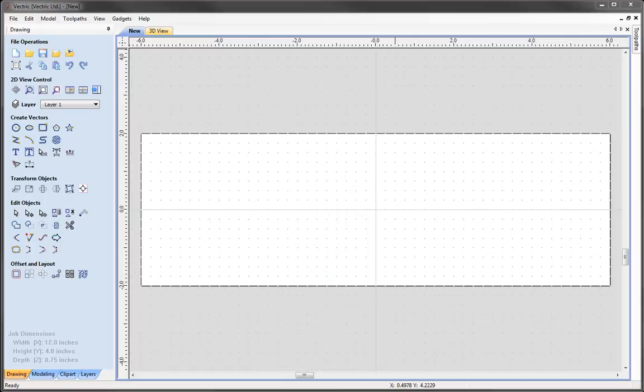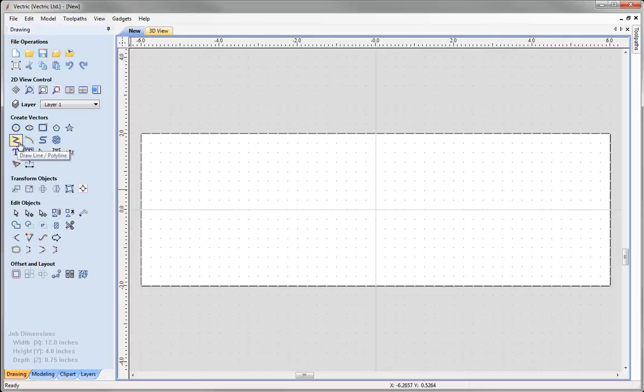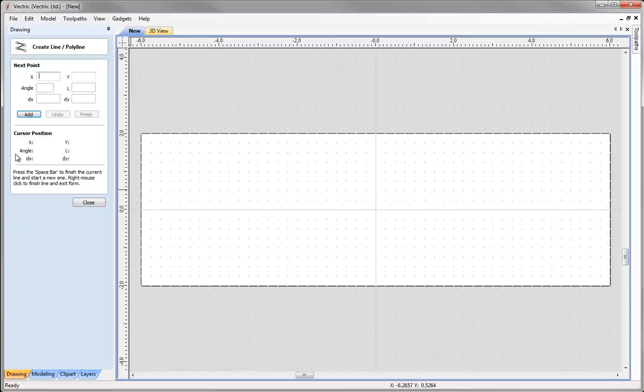So the first vector that I want to create is a line that's going to run along the bottom of our part, and we're going to use that as a rail for modelling the part using the 2-rail sweep. So to help me do that, we're going to use the Draw a Polyline option, which is this option here. So I'm going to select that, and we can see that that's in the Draw Polyline mode. Now if I hover over any one of these dots, you can see that the cursor is changing. It's allowing me to snap to a point.